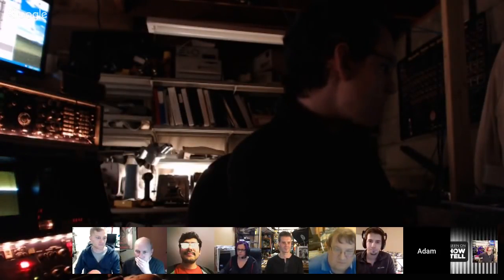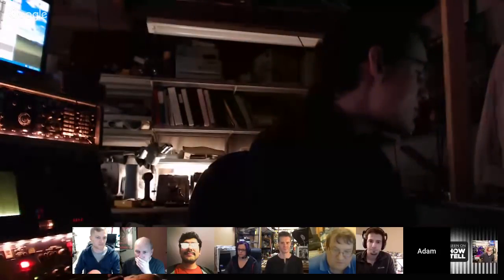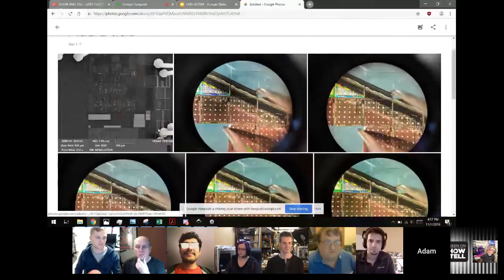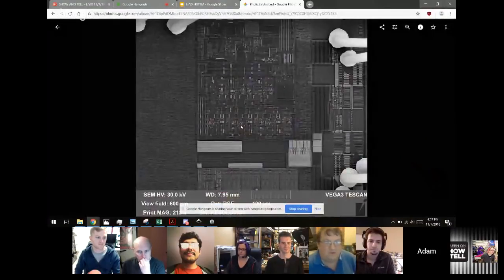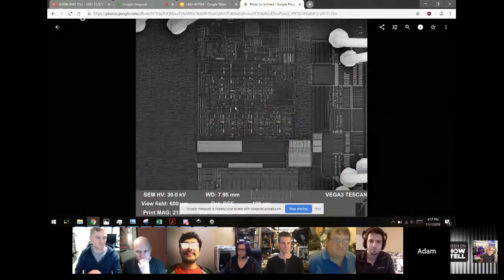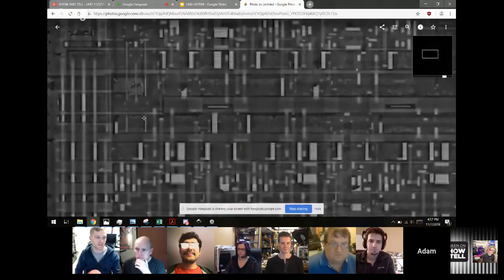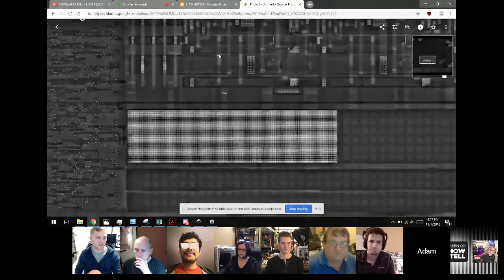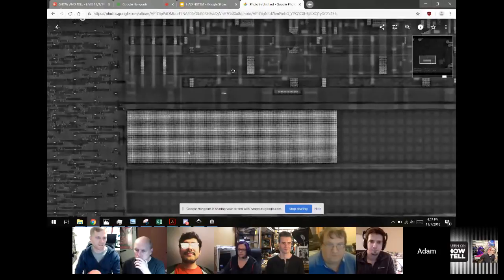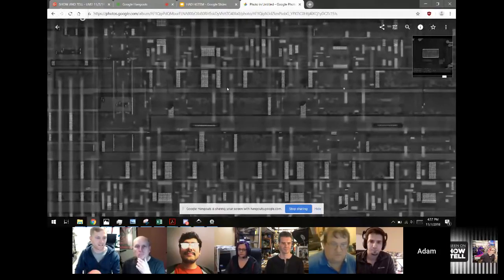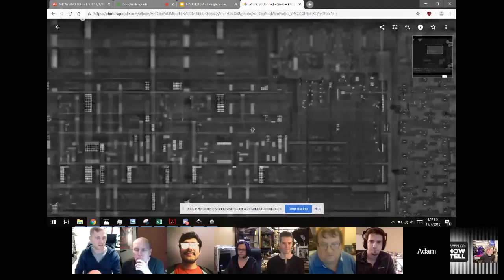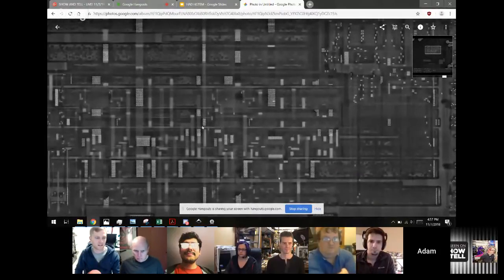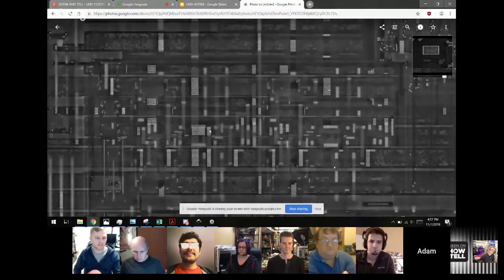Yeah. Cool. This was unfortunately not captured with my microscope. I got to use a brand new microscope at a conference recently, and this one's interesting just because of how high resolution it is. We can just keep on zooming in on this thing and see some really interesting stuff. What I did is I ran the beam at a very, very high kV and extracted a specific type of electron that lets me see through the surface of the chip. So you can see there are some parts that look pretty translucent.